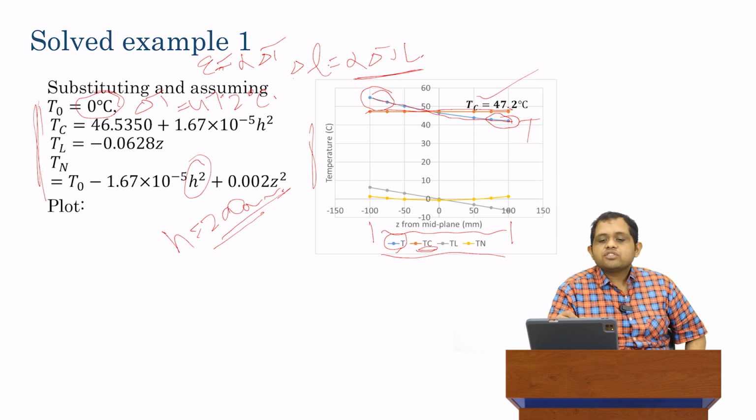However, in this case, there is no stress. We are mainly aiming to calculate stress, not the amount of expansion. There is no stress in this case because we generally assume that the base friction is negligible. So this is the amount of expansion that the pavement wants to make and is also free to make. So because the pavement is free to make this amount of expansion, there is no additional stress from this component.